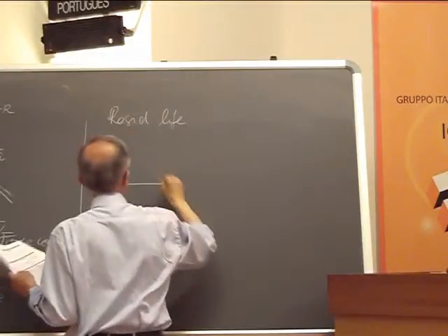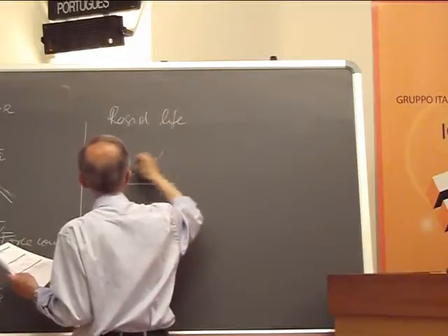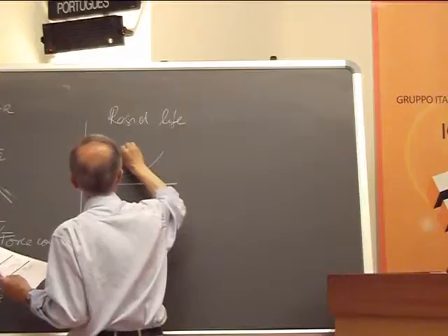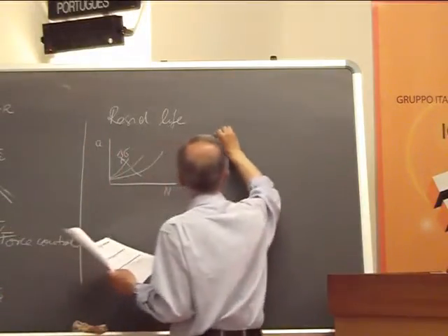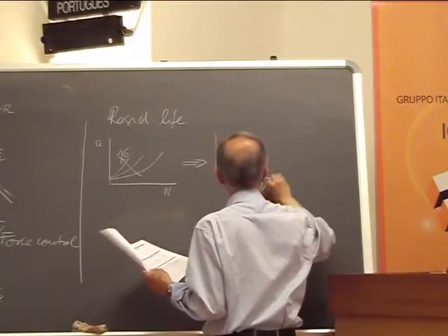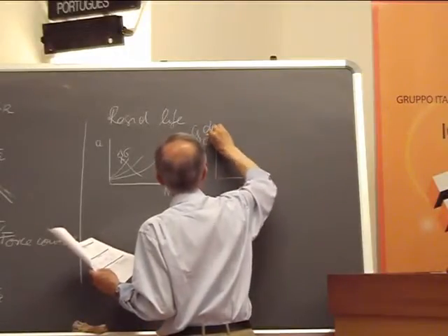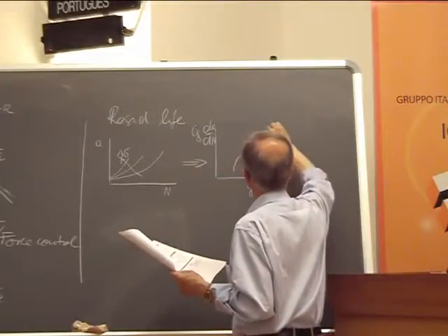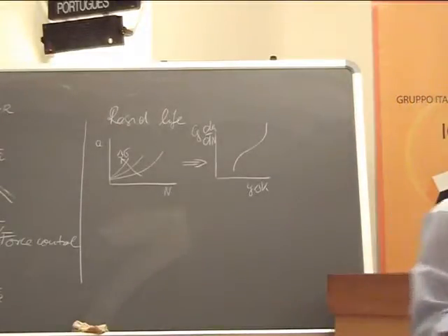We measured in an experiment A over the number of load cycles for various stress cycles or whatever, and here we end up with this nice S-shaped curve, logarithm of delta K, logarithm da/dN. So all these curves collapse into one curve if we do it properly. And so this is our material property.